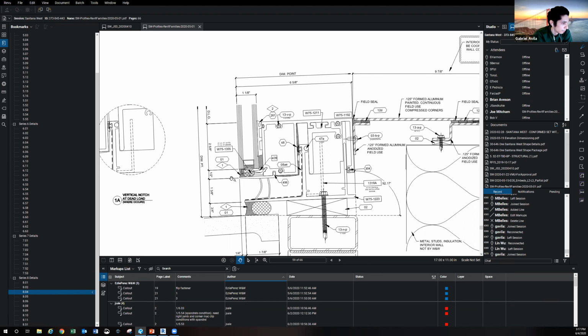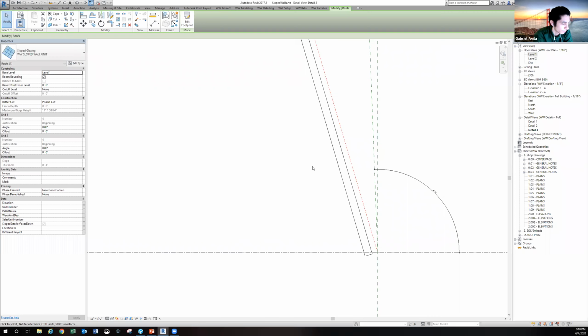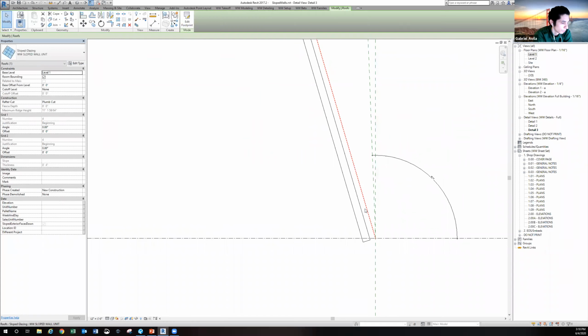Looking at this, the size of this sill member, which I got from the family, is 3.5, because it goes a little bit below the sill member, 7/16, I believe, or I forget what the dimension was for this one. So it's 3.5, and then the rest would be 1 3/4. I'll show you what I mean by that.